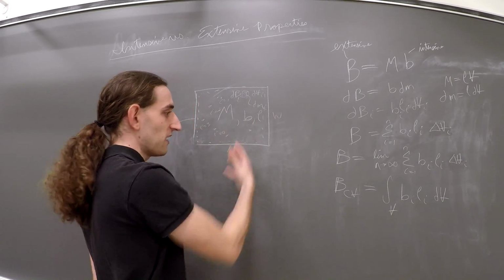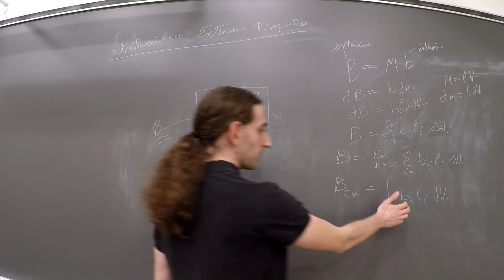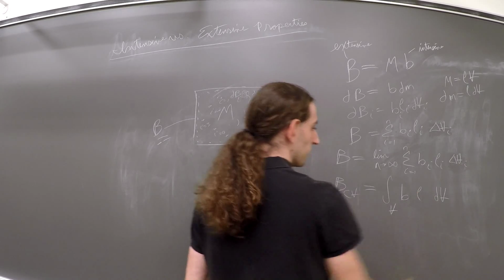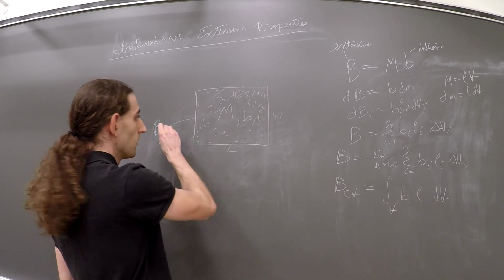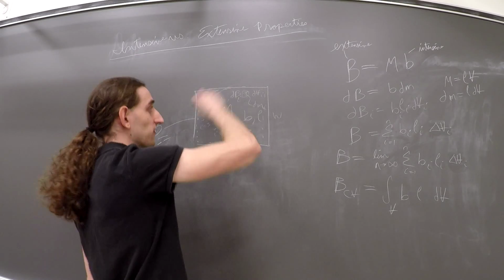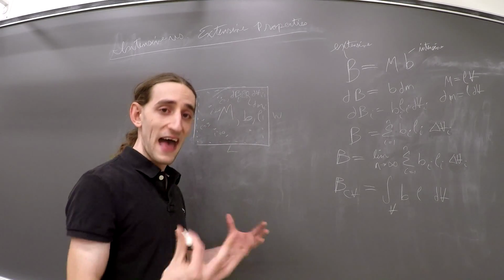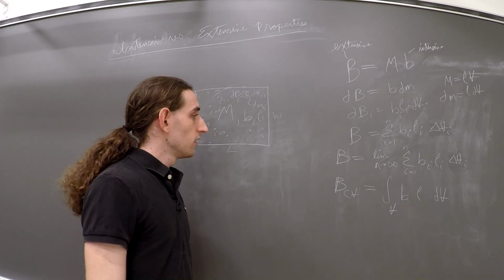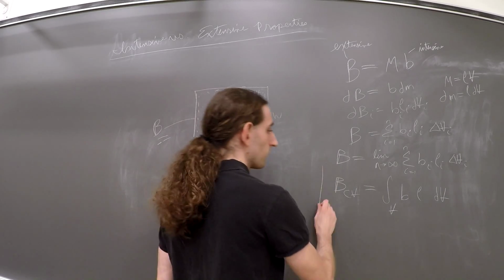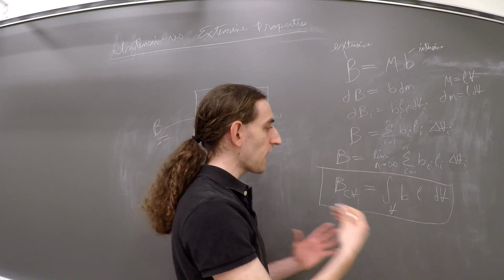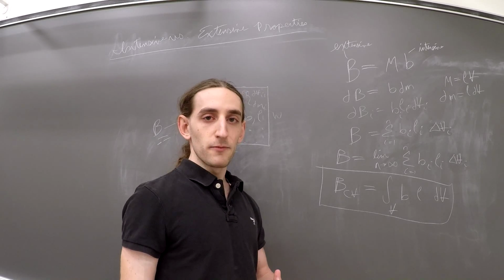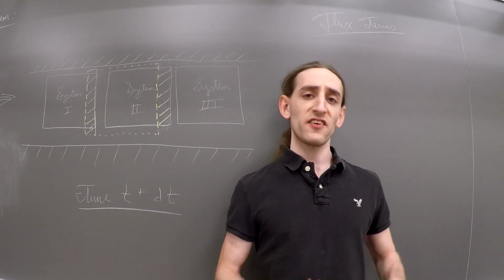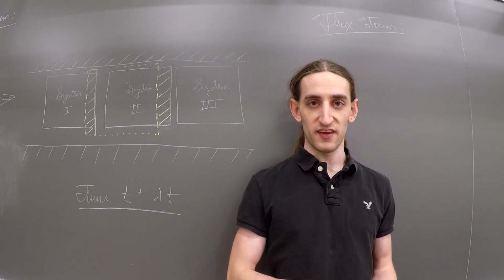So that allows us to figure out any kind of property B in this system by basically performing a geometric analysis. If we know the intensive property, we know the density, okay? We can drop these i subscripts here. We can figure out the total amount of property B throughout this entire region, and we can do that for what we're analyzing in the previous example I showed. We can apply this nice property to the problem we want, and that will allow us to derive the Reynolds Transport Theorem.